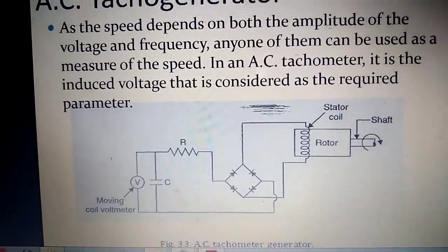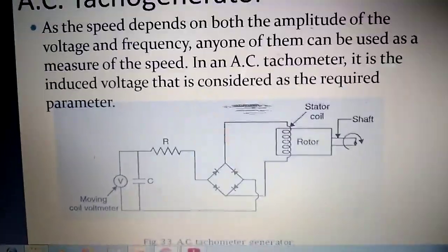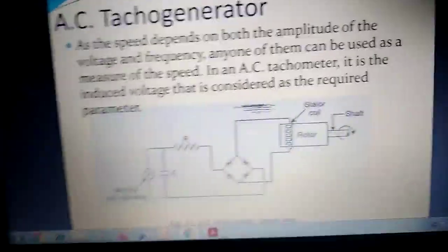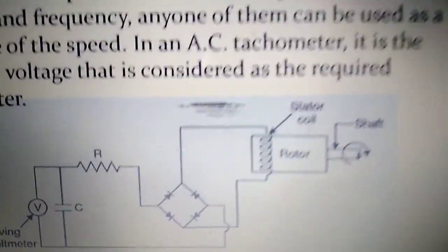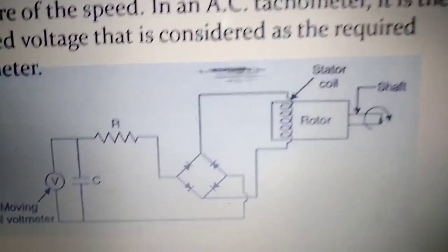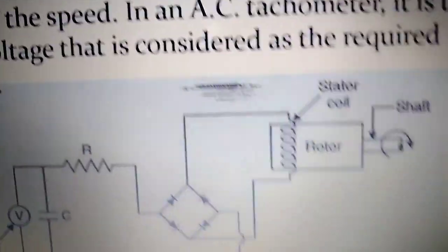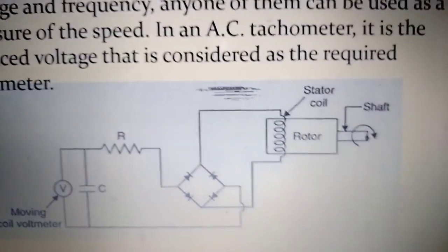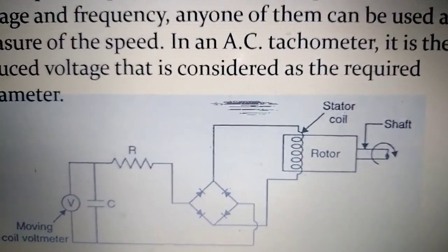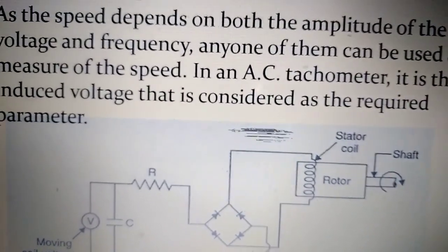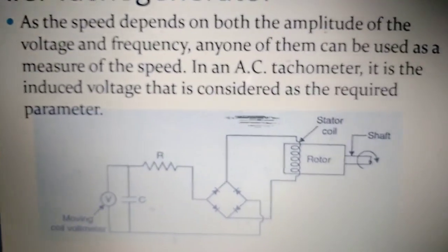In the constructional working, a cylindrical magnet is placed inside a conducting coil, or armature. The rotating shaft of the object whose speed is to be measured is attached to the magnet. If the shaft moves, the magnet also moves, so in turn a magnetic field is induced in the coil. The coil produces a voltage corresponding to the speed of the shaft.